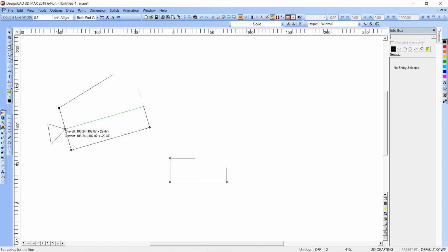VJS, enter. So VJS, it'll tell me that I want to do this line same as that one. And then I can hit E here, and then right click there, same thing. Control Z. If it was longer, so Shift underline, Shift underline. So now I just extended those lines. And E also will trim it to there.